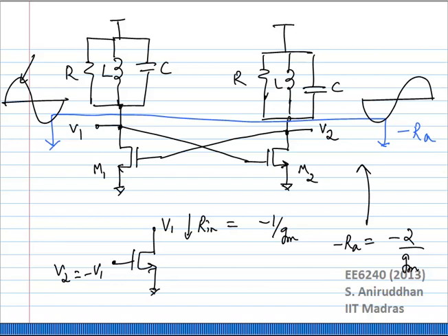Correct? To get the circuit to oscillate, in other words, to get the positive feedback to actually have effect and start up the oscillation, I need to provide some kind of asymmetry between the two halves. Otherwise, the circuit will remain at this metastable point that it's at. Okay? Is that understood? Does that make sense?